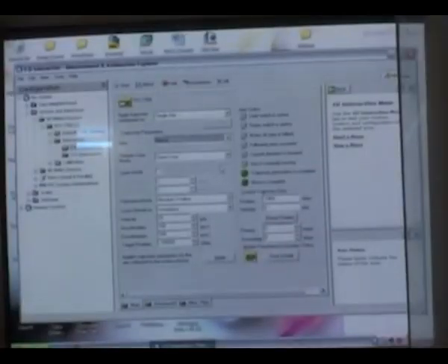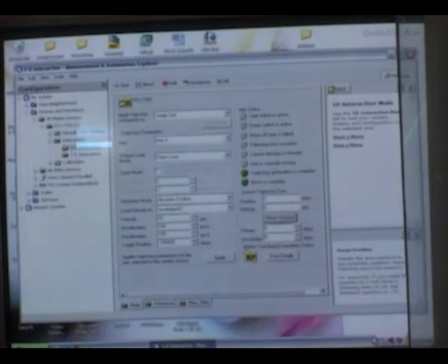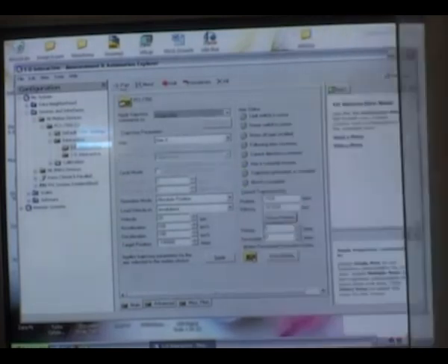Now I am showing you the motion of the Z axis. I have configured here axis 8, which is connected to the Z axis. The velocity I have maintained is 20 rpm, which corresponds roughly to 1.6 micrometers per second, and the negative direction will show it going upward, as you can see over there.